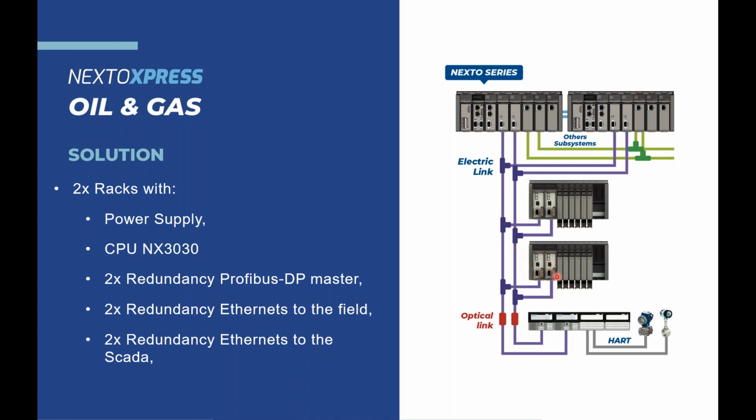Let's say that we have now a major fail, and one of the modules from this rack fails. So module B of the second rack fails. What will happen? The system has to make a choice. Okay, I will keep rack 1 working, or I shut that down, or I have to do something with this one. So the system will fail in some of the racks. There is no other way. You will lose control of one of these two racks, either the first one because of this cable, or the second one because of this module.